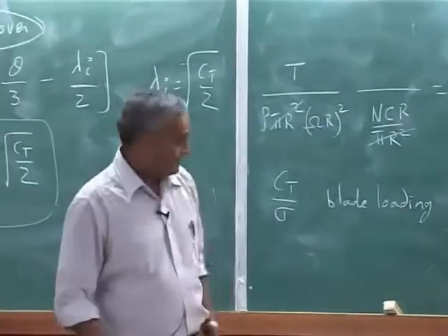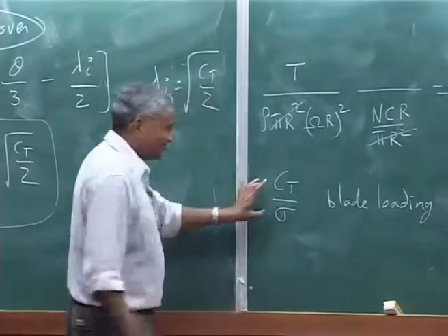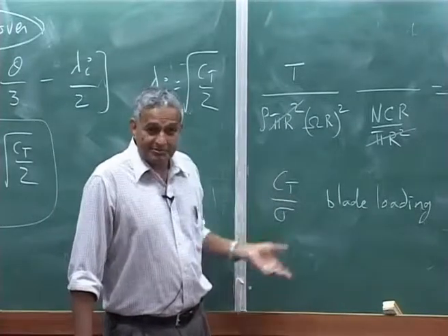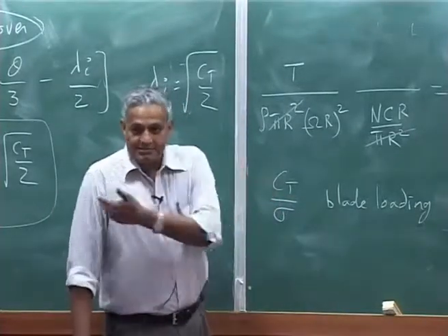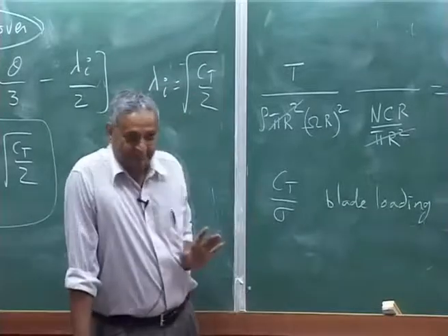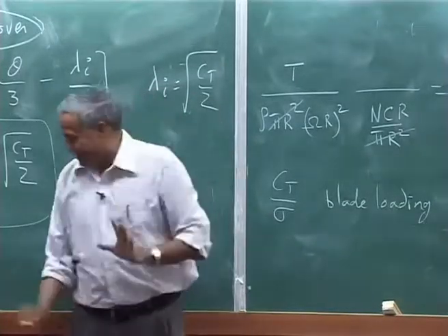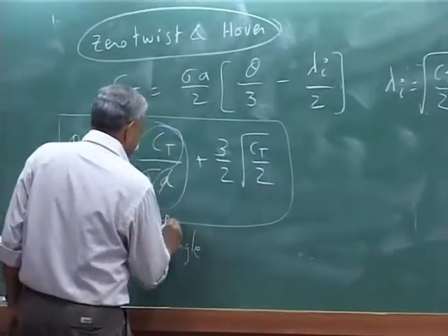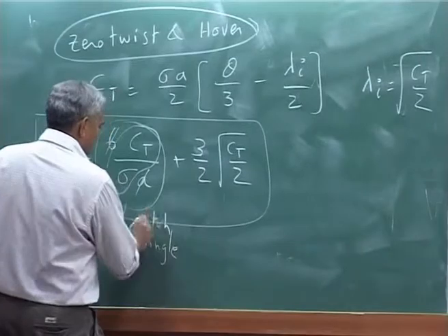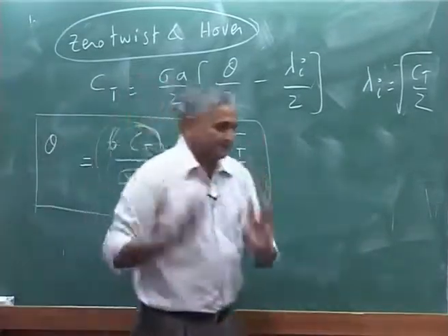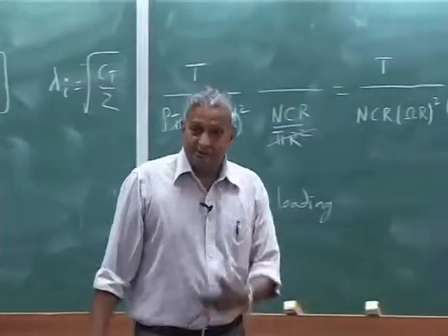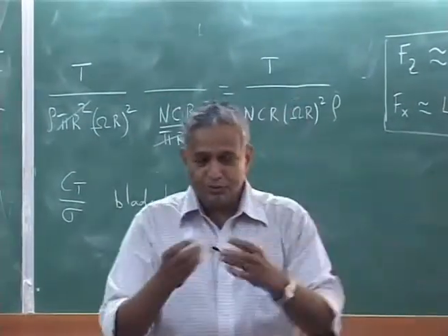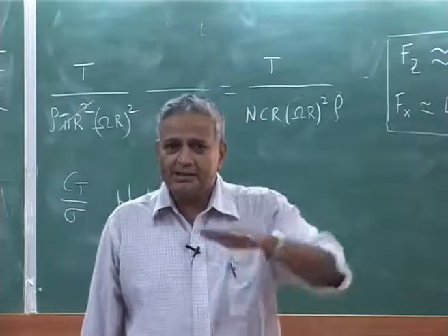Now, I want you to note down this particular quantity. You may call it blade loading, you may call it the mean angle of attack, actually it is the mean pitch angle. I think mean pitch angle would be a better term, the mean pitch angle required for operation. Please understand, this is just for you to know, we are talking about hover.